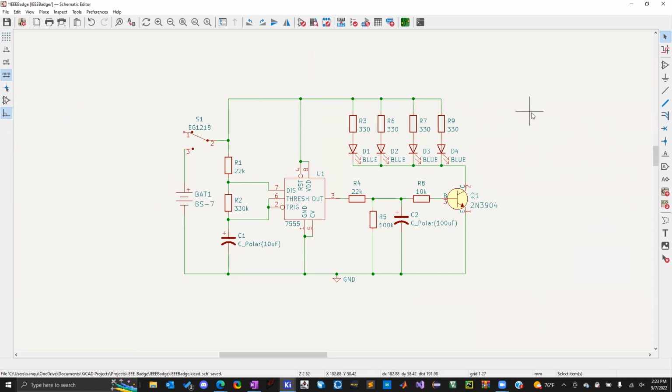We'll work with that a little bit more when we get to the layout because there's some common millimeter distances like 2.54 millimeters, 0.254 millimeters, 0.0254 millimeters, and those are varying amounts of mils. So that's like 1 mil, 10 mils, 100 mils. It makes things nicer than 2.54 millimeters. You can just say 10 mils.